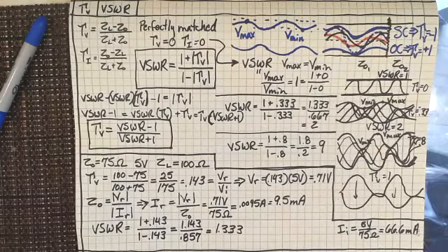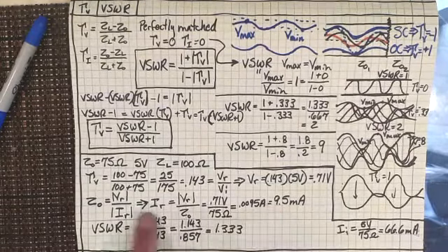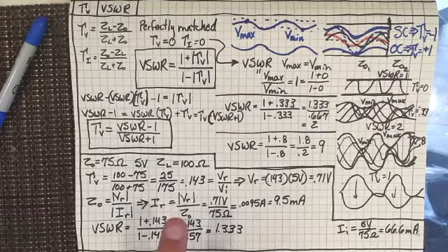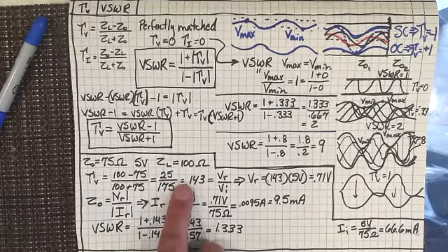You know, we would set up a standing wave and that would cause a lot of problems. Let's just say if it was a TV signal, you would not be watching that channel right now with that type of interference. It would be a wavy channel. I just want to point out also that this impedance mismatch is what they used to use to block channels.